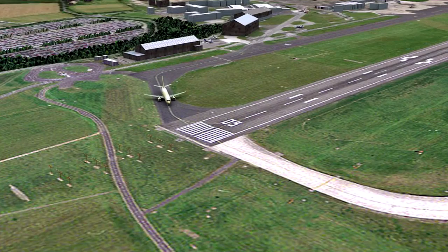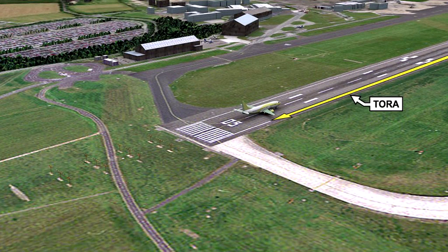For instance, large aeroplanes will use a portion of the runway to turn and line up ready for takeoff. As such, the start point of the takeoff will be some distance in from the edge of the pavement. Due account of this must be made by the pilot. In such cases, the actual takeoff run available will, of course, be less than the paved runway length and the distance between the thresholds.